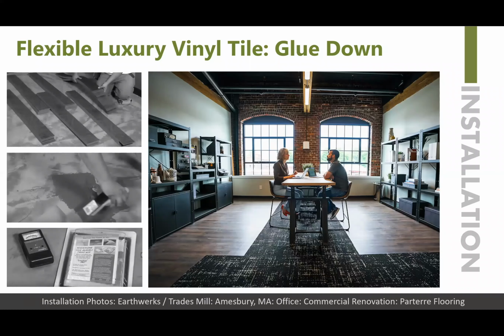So you want to acclimate to the installation location, humidity and temperature level before installing LVT that is expected for the finished space. Separate into small piles of LVT planks. So you want to be very aware of that when you're getting ready and part of your specification to understand what is the pre-treatment of the product as well as the subfloor treatment to make sure that everything is aligned and ready to go for a successful installation.